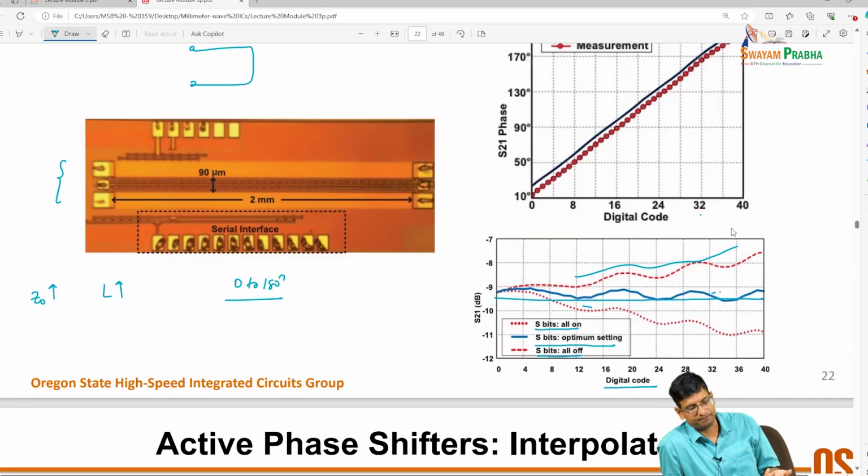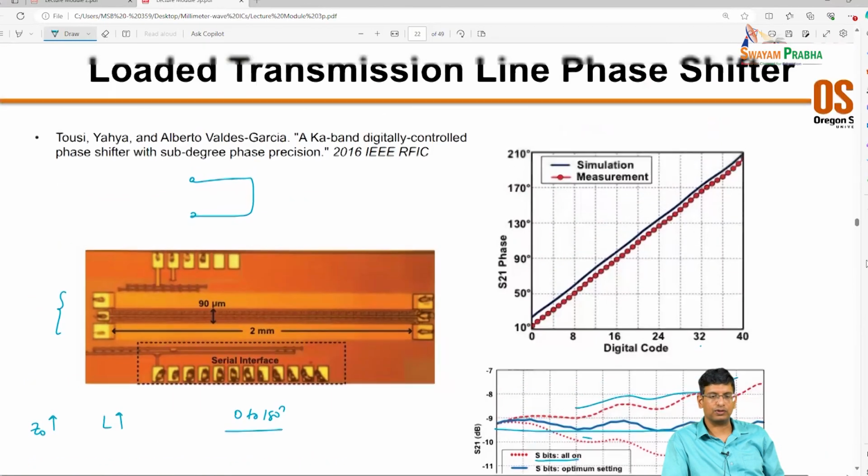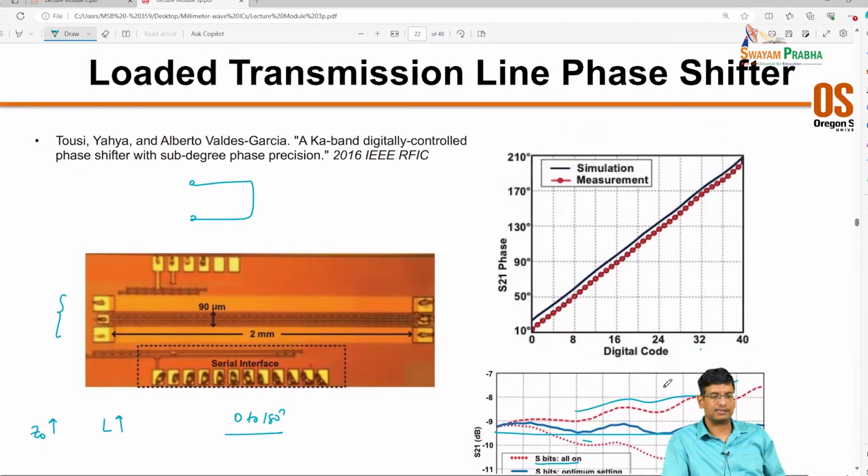One of the things that they have in this paper also is that they look at how the phase shifter behaves across multiple samples of the chip, right? And their observation is that this is a fairly uniform phase shifter across process, though sensitive to PVT, right? But even in this approach, it requires a hybrid approach because you're starting with 180 degrees.